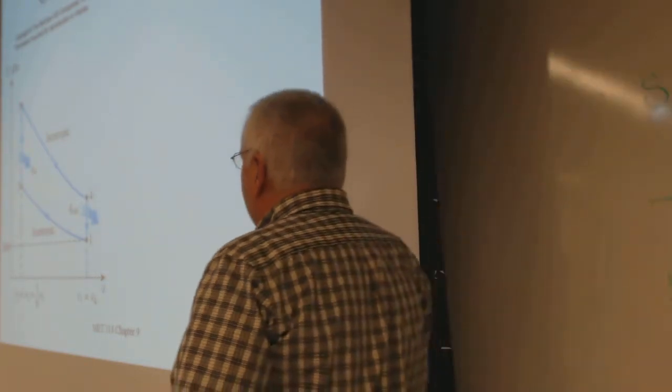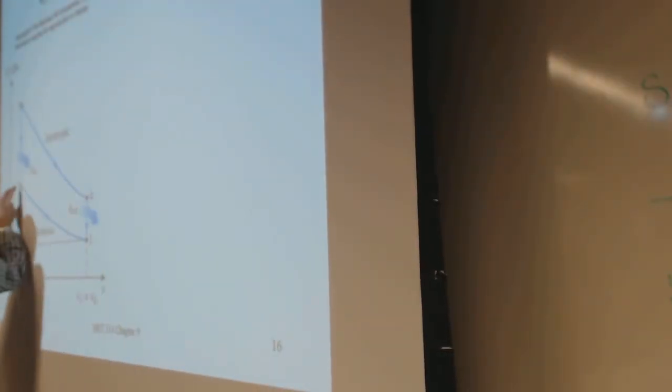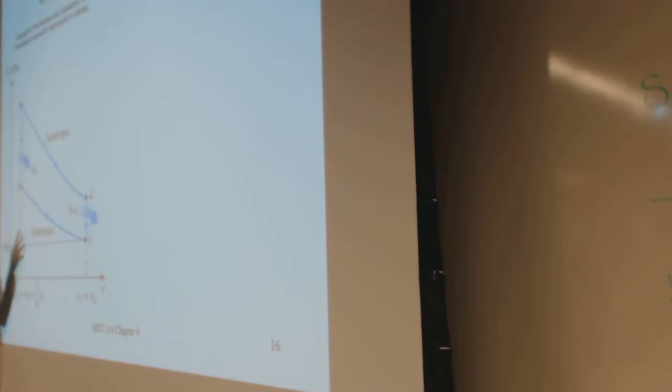So we've been talking about this Otto cycle. It doesn't matter if we're talking 2-stroke or 4-stroke engine, but we had an isentropic process that we're modeling, and this is ideal gas world, so it's going to have a formula with K's in the exponent.